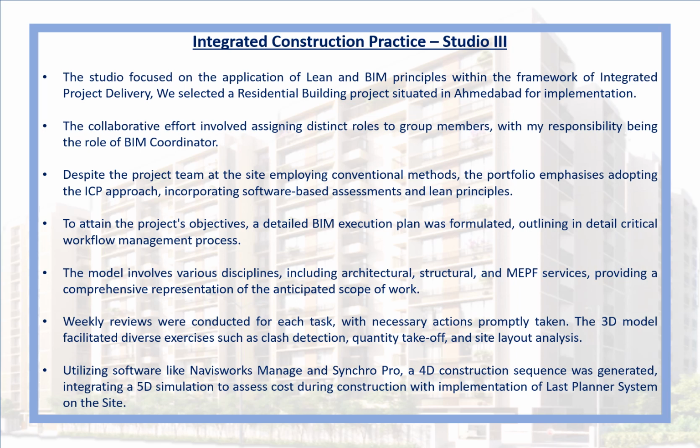The 3D model facilitates diverse exercises such as clash detection, quantity takeoff, and site layout analysis. Utilizing software like Navisworks and Synchro Pro, a 4D construction sequence was generated, integrating a 5D simulation to assess cost during construction, with implementation of last planner system on the site.